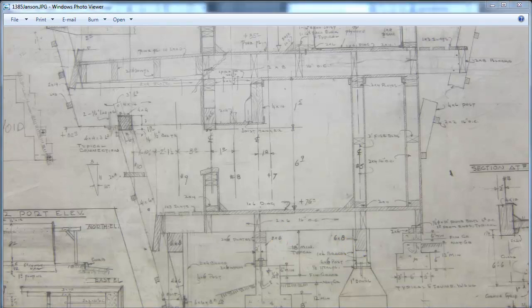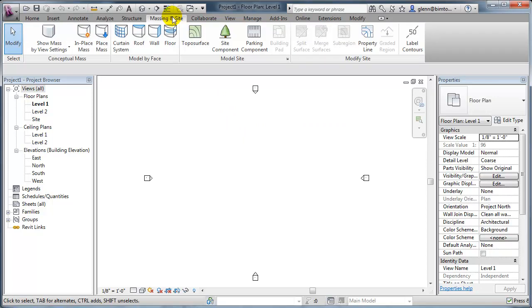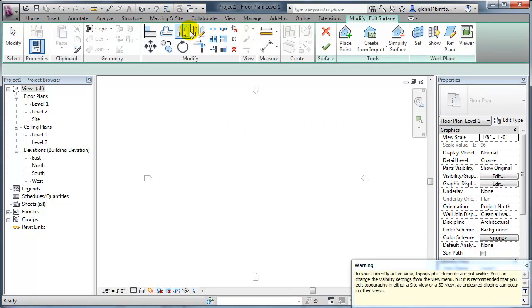Switching back to Revit, let's get started by modeling some of those foundation elements, and then we'll start building the walls on top of them. For what we're going to do, I'll build a standard little foundation, a prototype. It won't be specific to any of the houses, and that's going to be okay for getting started. Let's start by putting a little bit of site down for ourselves.